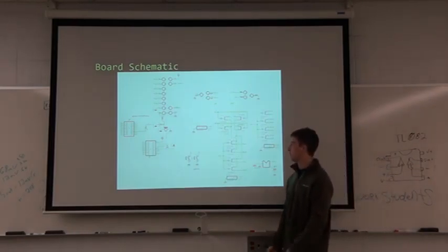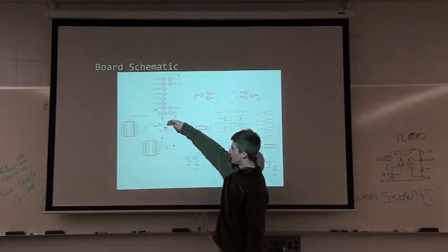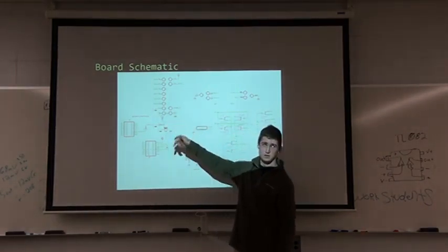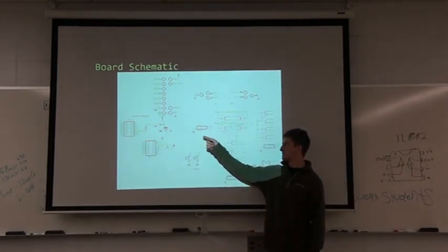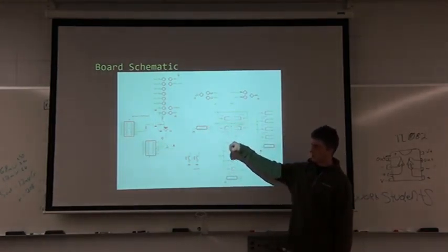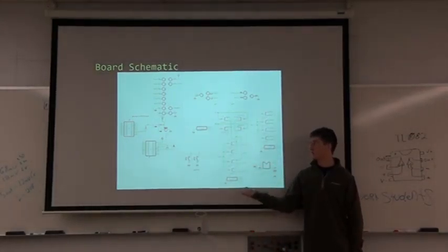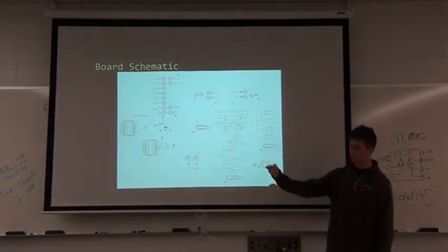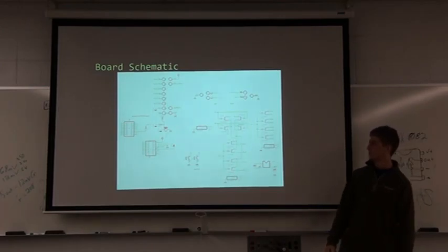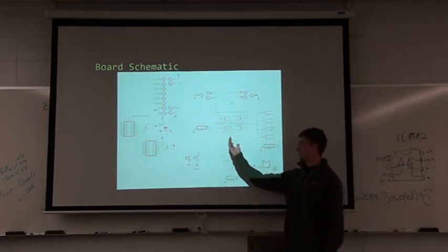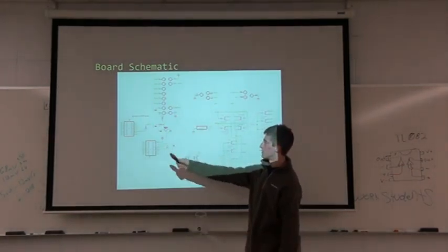get wiped out. The only other two things are the resistors for the gate on the transistor, and so since the gate requires milliamps of current to run, to close and saturate the MOSFET switch, I chose a 1 k ohm resistor, and then it's a 10 k ohm ground.